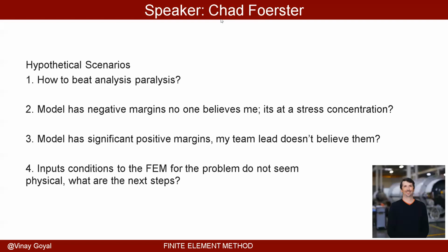Is your model truly right? Have you done that deep dive and really looked at the pre and post? Both are super important. Go down and look at the integration points on the elements in the post processor, see what's going on, and see how it's visualizing your results. Maybe it's doing something funky, like node averaging, or something that you don't even know it's doing, and it's showing you something that's not real. Really, the integration point is what you want to look at sometimes.